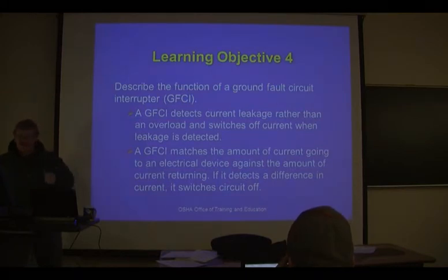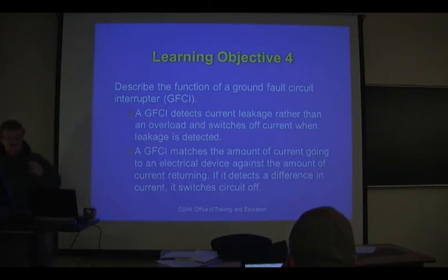You might have a crack in, you know, a motor. All your wires are insulated, right? They're dipped, laminated. You might have a crack there, okay? Or you might have a wire that's, through vibration, rubbed through its insulation or something like that. So a GFCI trips on leakage, and there's actually two types.